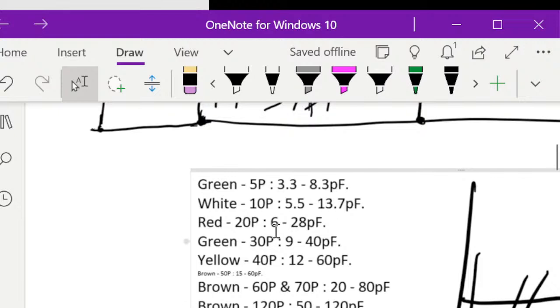Now, if you have all these values, and I do have all of them, after my calculation and choosing a random R, well, not really random in that sense, it was an educated guess, and choosing the yellow one, I knew that this bounds my frequency. My frequency range is from 19.19 to 56.86. So I chose the yellow one. That's the reason for that. So as I vary it, I can cover the entire AM band.